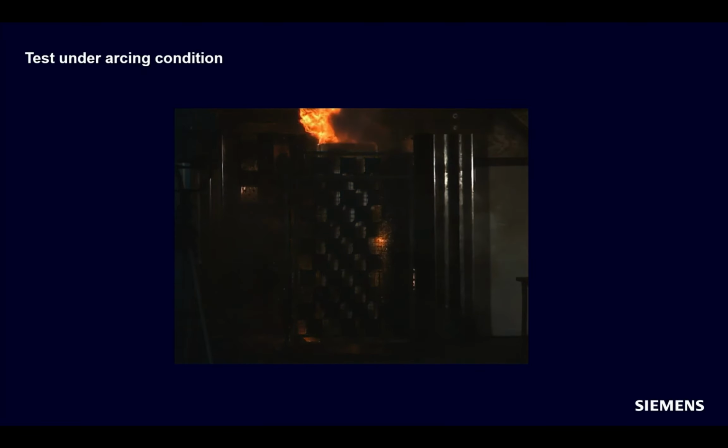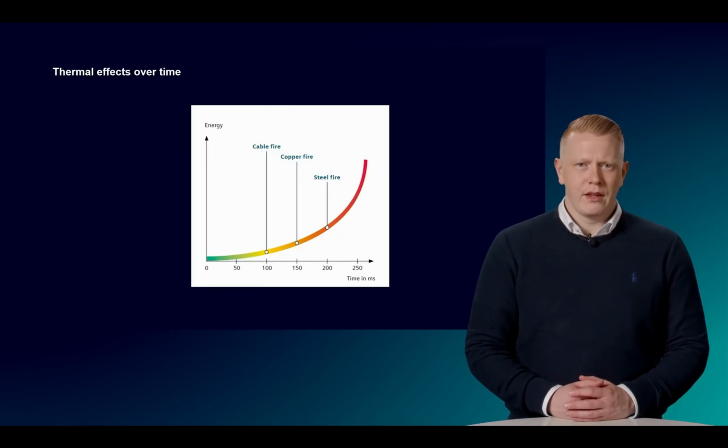In the last section, we discussed how we can use passive and preventive measures to limit or even avoid an arc fault. However, when limiting the arc fault with the help of passive measures, an arc flash burning time of 300 milliseconds can be expected. This duration in an event such as an arc fault also means a very high energy conversion.